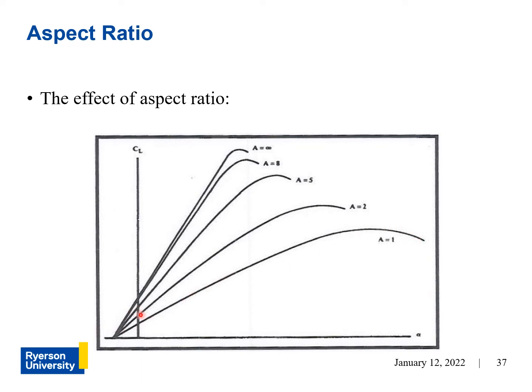So in a way, because it's seeing a lower angle of attack than it should, then it'll take a higher angle of attack for it to stall, and vice versa for higher aspect ratio wings. It will tend to stall much sooner, at angles of attack that it will actually stall at in comparison to this one here.